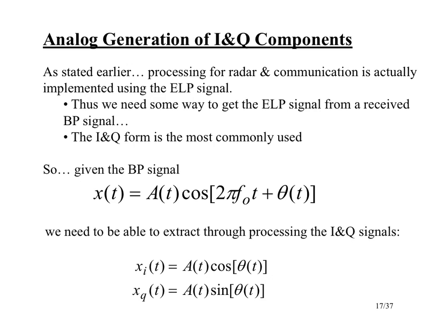And so basically, the equivalent low-pass signal is a complex-valued version of one spectral side, the positive frequency side of the signal, shifted down to be pretty close to DC. It usually straddles DC, but not necessarily in any kind of symmetric way.